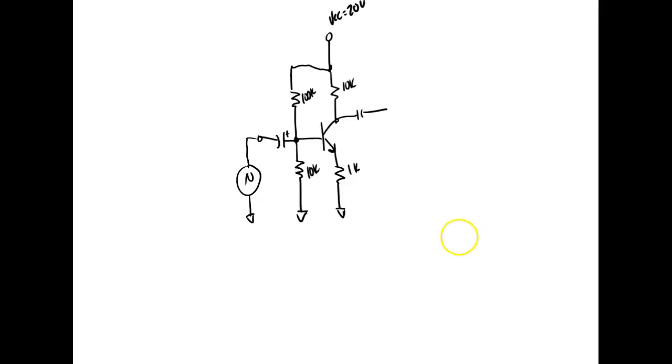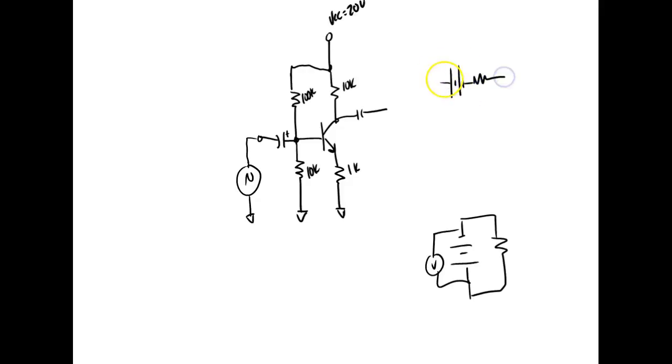So this is why, if you go out and buy a C cell, and you take your voltmeter and put it across it, and then you put a 100 ohm resistor across it, what's the voltage going to do? It's going to drop. Well, what's dropping it? The internal resistance of the voltage source. So all sources basically look like this. And then, of course, what we see over here is the plus terminal and the minus terminal.